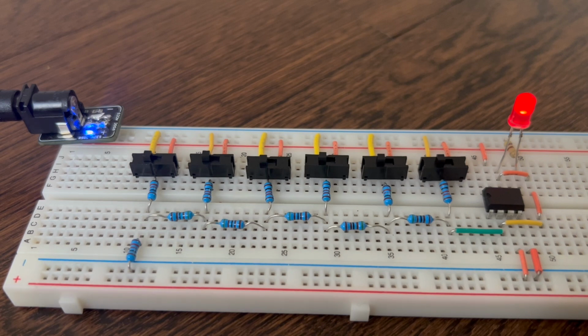In such a scenario, theoretically, the op-amp can produce output voltages ranging from 1.5 volts to 4.5 volts, and consequently, when the DAC outputs 0 volts, you might expect a 0 volt output. However, due to the constraints, it typically generates an output close to 1.5 volts.